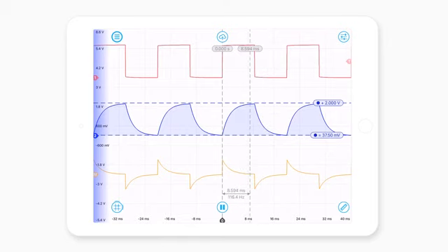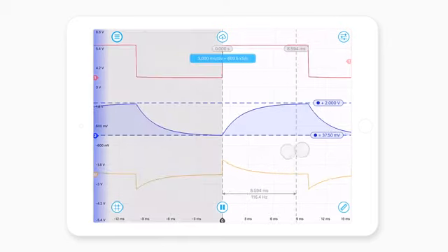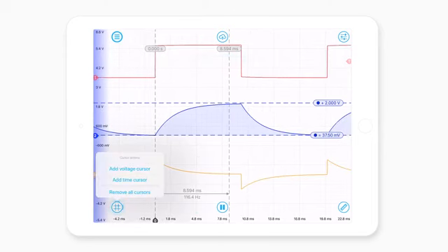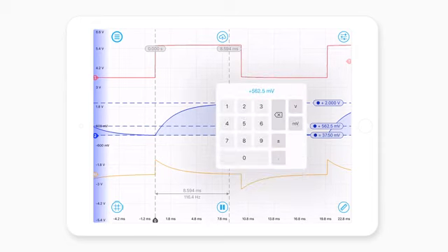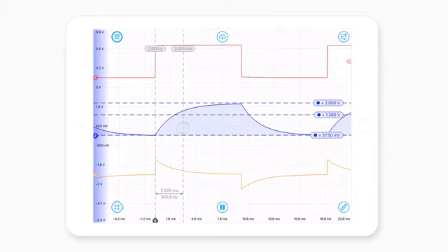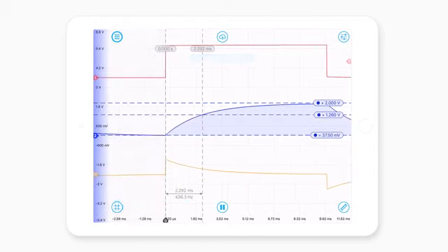Alrighty. So let's have a look at this time constant. The time constant is an interesting thing to measure for an RC circuit because it tells you a little bit about the low pass filter characteristics. I know that in this case, I'm looking at something that's at 63% of 2 volts. I already know that that's about 1.26 volts. And what I'll do is I'll just quickly drag this time cursor over here, and we'll say, okay, we're looking at a time constant of this particular circuit of around 2.3 milliseconds.